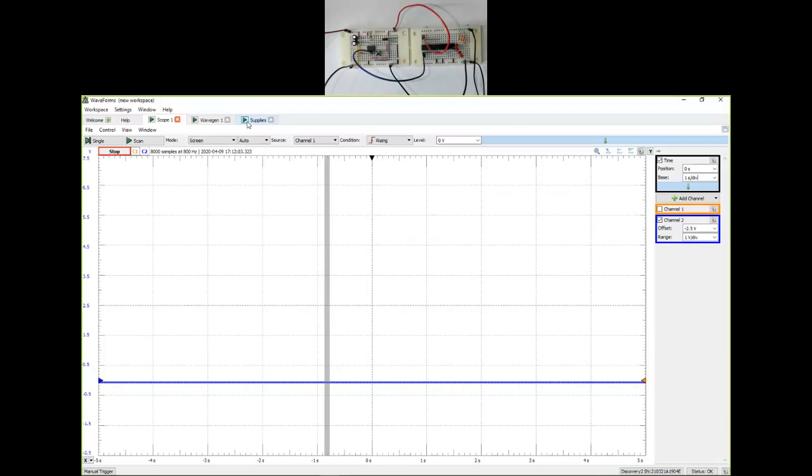So let's see if I turn on the supplies now, will I be able to count exactly in order or not? So I've turned the supplies on here. Press once. 1, 2, 3, 4, 5, 6, 7, 8, 9, 10, 11, 12, 13, 14, 15, back to 0. So now it has gone through the exact sequence without any skipping of state, without jumping states. It has gone down slowly. So we have got a very good debouncer circuit working here.